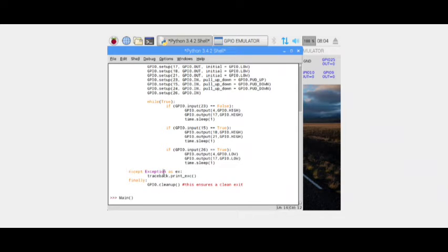And then we use except exception as e, so that other exceptions, and the traceback, are handled when GPIO pins are not involved. We write traceback print exc, and finally GPIO.cleanup, with which we ensure a clean exit of the GPIO. And for the last line of execution we put main.